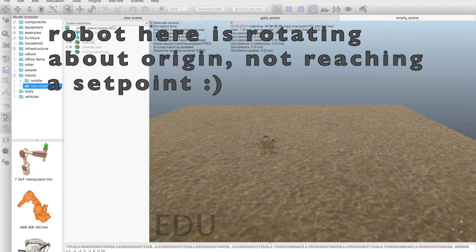We first tested the mechanical frame and thruster placements in simulation, and we found that the robot achieved 6 degrees of freedom without much trouble. Then we tested the controls algorithm in simulation. Our main victory was validating the new nested PID loop's ability to move the robot to a desired position or a velocity set point. Our robot rarely overshot the mark when it came to attaining a given set point.